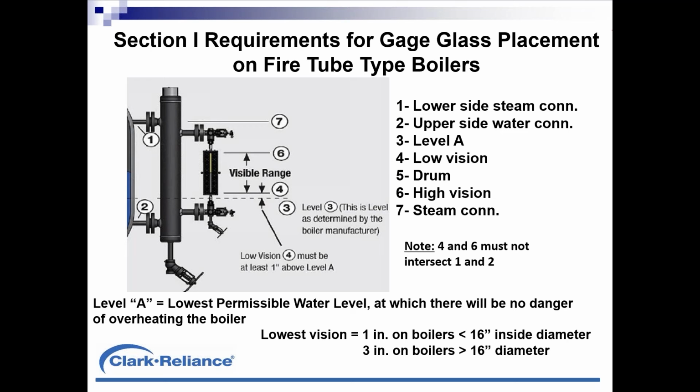So this way, when you shut your boiler down, you've still got about a 2-inch safety bed of water in the boiler before any damage can occur. Simply put, you wouldn't want to trip your boiler with a low water cutout just as it's about to be suffering damage without some cushion or safety factor.